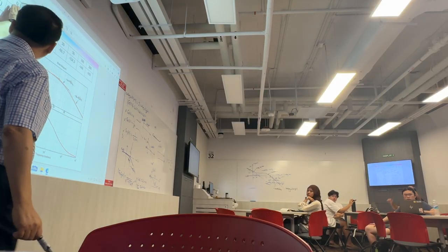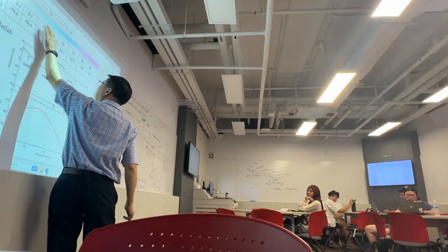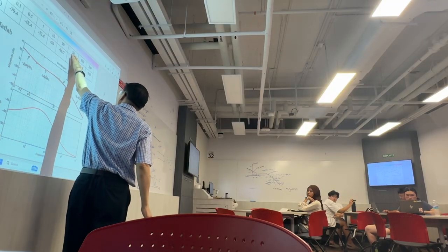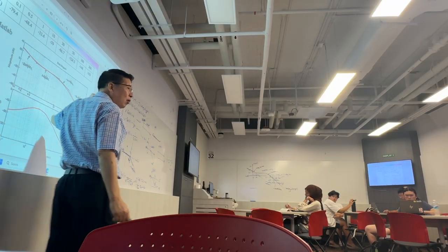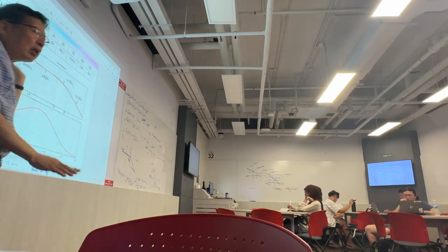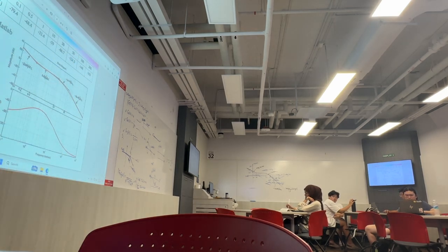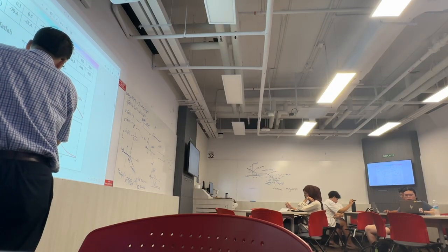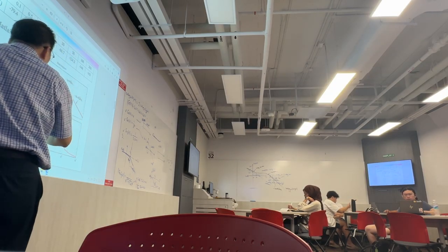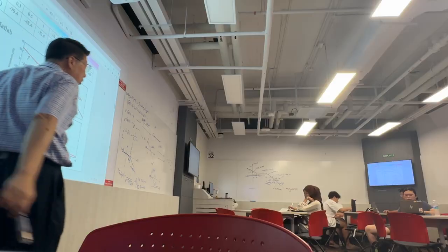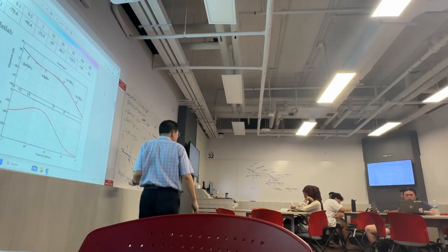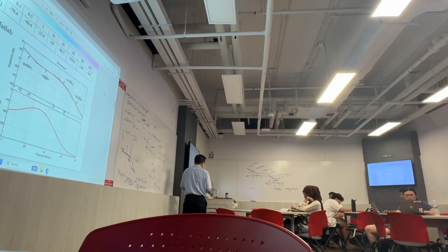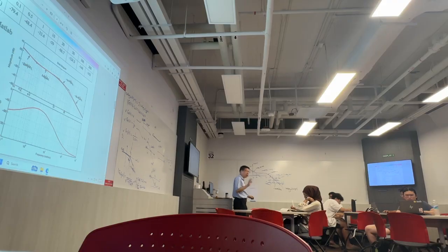Then the 0.1, and 10, and 0.5, 10, 50, and somewhere larger than that. In between, it actually doesn't matter too much. Then you plug into the formula we have shown, get a sequence of points, and then connect them by a smooth curve. That's good enough. Don't use a single straight line for the phase.